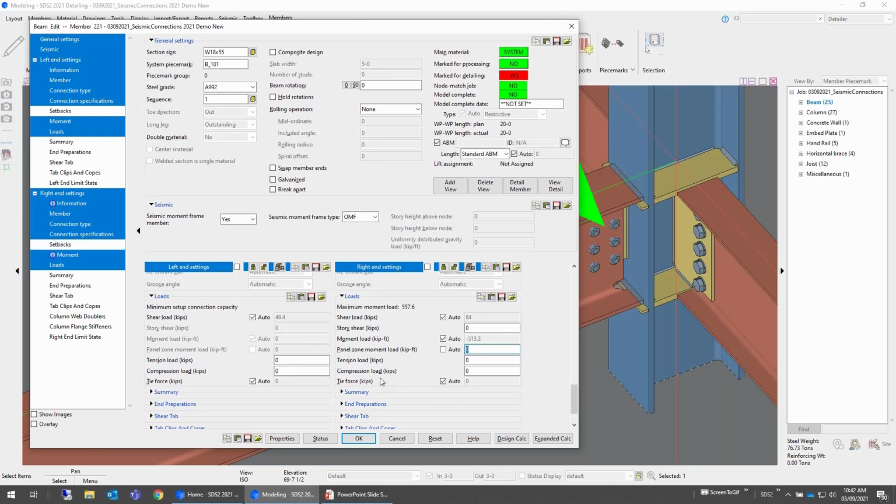If you mark that auto, this is another thing where that load is, according to the manual, supposed to be based on load combinations. So it should be based on an actual design moment, but if you mark that as auto, we just populate that with the same magnitude as that one you're hovered over above there, as the regular moment load there, right. Okay, good information to know. And there should be a design note on the report to that effect that calls that out to your attention.